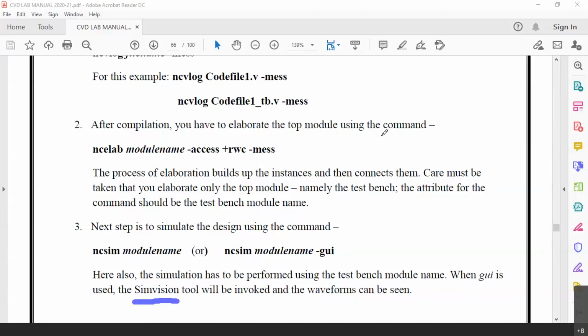As I showed you earlier, in analog designs, we had Virtuoso schematic editor, then we had a Spectre simulation. Spectre was the tool which had one ADE, analog design environment, where we used to specify transient analysis, AC analysis, DC analysis, and the tool used to plot the graph. Here in digital domain, there is nothing called transient, AC, DC. It is basically transient only here. We will not be seeing any DC and AC analysis here because this is purely digital. So we can say here it is a transient analysis.